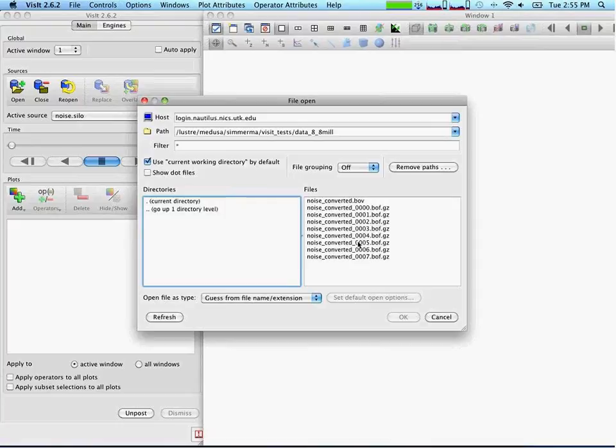So, as I talked about earlier, once you review it, it's easy to come up with your own format. The VisIt documentation has details on how to do that. If you have your simulation spit out raw data, it's easier than this format. Basically, you have your raw data in some files, and you have a little metadata file that tells about the structure of that. So here, the metadata file is this .visit file. The data are in these zip files. There are 8 of them here, so it's divided into 8 blocks. So we're going to read this in.